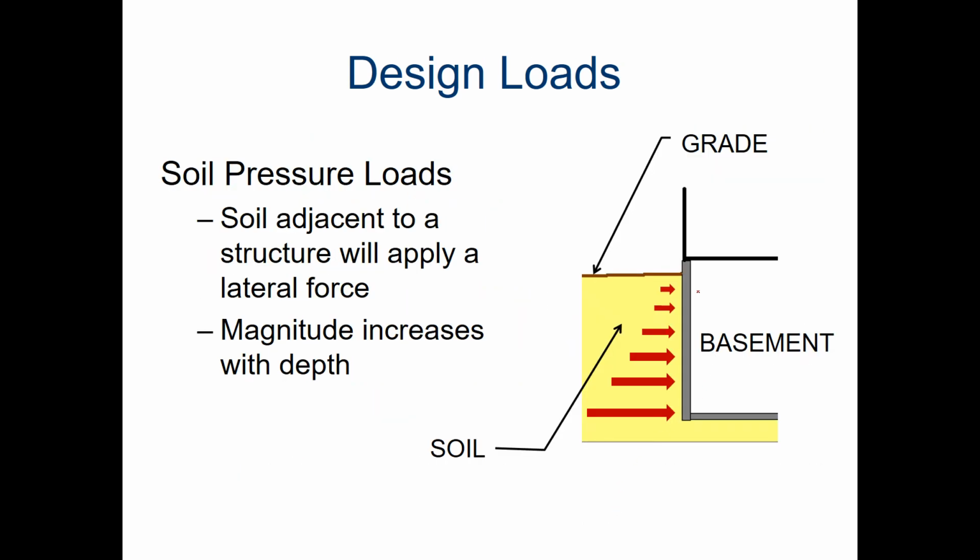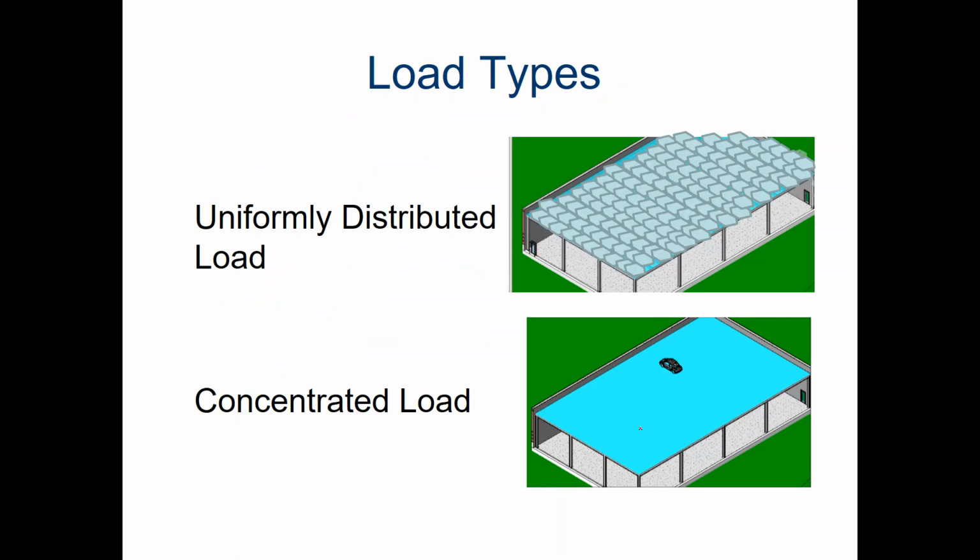Soil pressure loads. Soil pressure loads are a little bit like if you swim in a deep pool and you go into the deep end, you go way down, and you notice that the pressure is a lot higher the deeper you go. Well, the same thing happens with soil. And so if you have a foundation, the soil pressure is going to be greater the deeper you go down, because there's all the soil on top of it. All right, and so that's something that obviously that basement wall there, that foundation wall, needs to hold everything above it, but it also needs to withstand the pressure of all of this soil pressure pushing against the foundation wall. I think I'll stop there and pick this up in a moment.